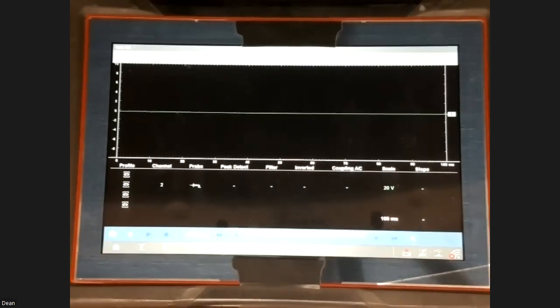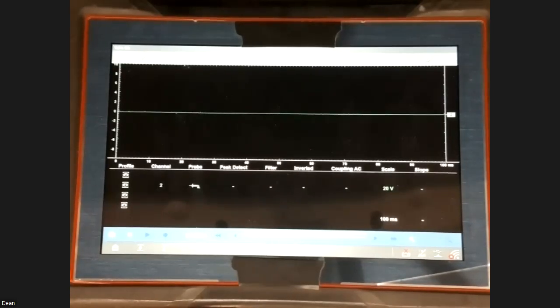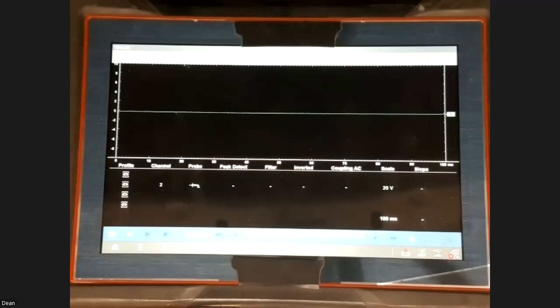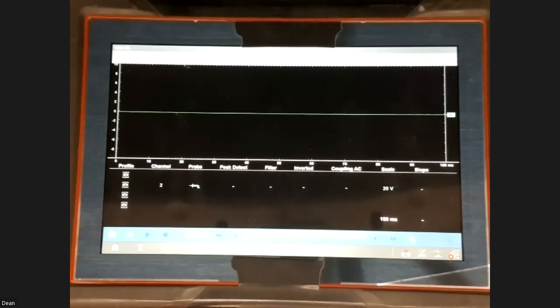But now here's the meat and potatoes of this part. What is reserve capacity? What that means is that it will supply the voltage to the system. All these computers on board are going to need at least, and there's a debate out there right now, anywhere between 9.75 to 10.5 volts is what most computers need today. So if we're looking at the PCM, the powertrain control module, that powertrain control module is going to need no less than 9.75 volts.